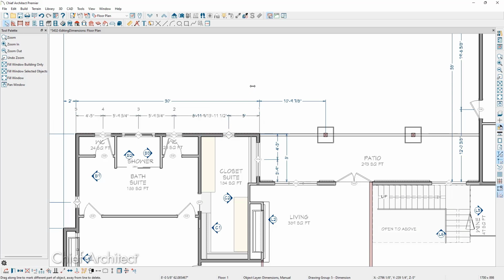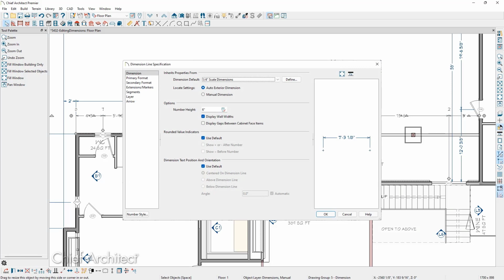If we take a diamond and unsnap it from an object and do not snap it to another object, it will disappear, removing the extension line from the dimension string. At the ends of the dimension string, we find circle edit handles. These are Add Segments handles. If we click and drag these handles, we can extend the dimension string and create new segments that will locate objects just as if we were drawing the dimension originally. It knows to do this by remembering the default used to create the dimension.